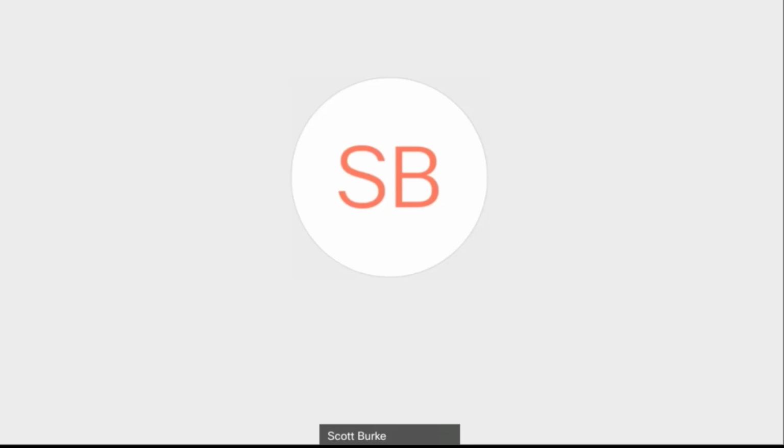So most firms will create a template project with the structure they want in it. And then when they create a new project, they pick that one as the template. That way, the new project they create will mimic the folder structure. So right now, that's limited to the folder structure, and any role permissions that you put in that template project will also be carried over. But individual permissions or company permissions will not, at least at this time.